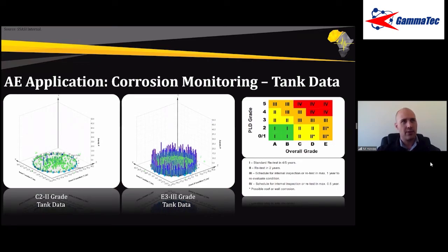Alternatively, in theory, you could load a bridge up with, say, water weights. So you pack water weights on there, load it slowly with water, and then you can stress accordingly, according to the procedures, and detect it. But it's most effectively used for long-term monitoring.